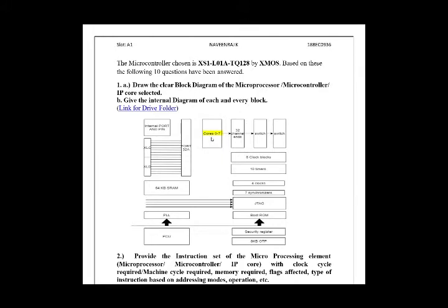The Xcore tile has up to 8 active logical cores, and these logical cores issue instructions down a shared 4-stage pipeline. The instructions from the active cores are issued round robin in no particular order.